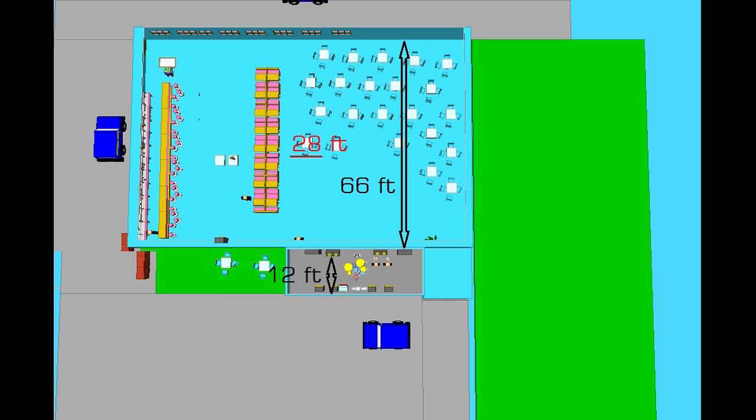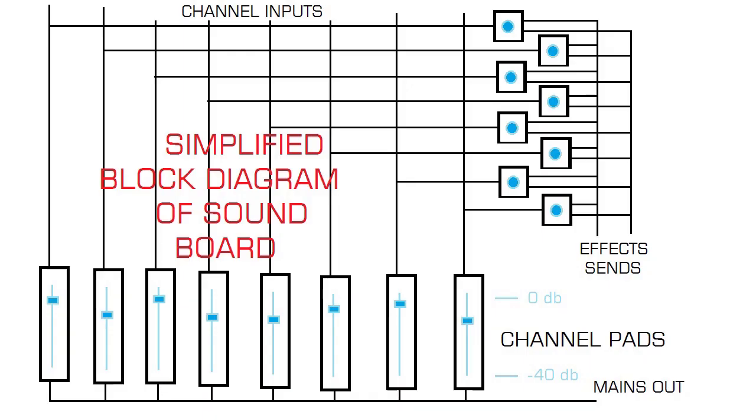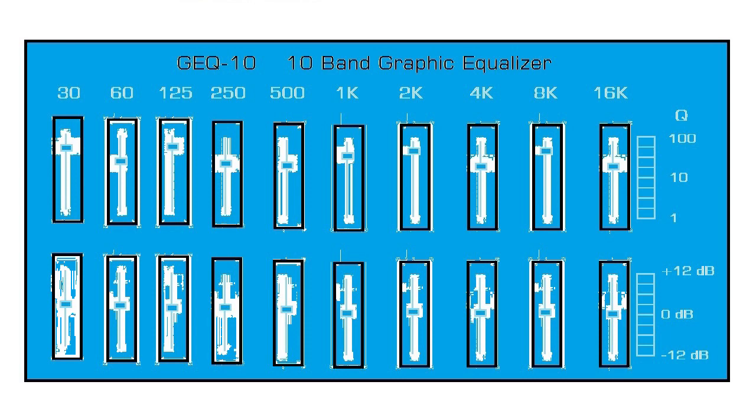The other side of the coin is, the reflection might arrive in certain spots in phase with the original wave and reinforce it, bumping the level of that frequency up a couple of decibels in that area. If a live mic happens to be there, this can cause unwanted feedback. This can be corrected with the EQ, but at some expense in sound. Bump the level of the mic back a couple of decibels until the feedback goes away, or use the EQ to bump the treble frequency down to kill it. Your sound may drop out at that frequency band, but the crowd won't mind.